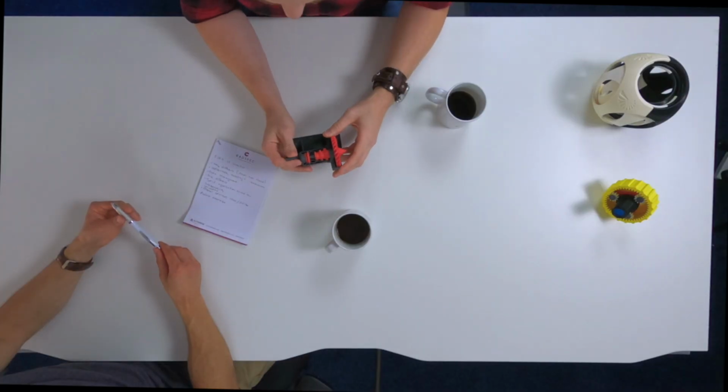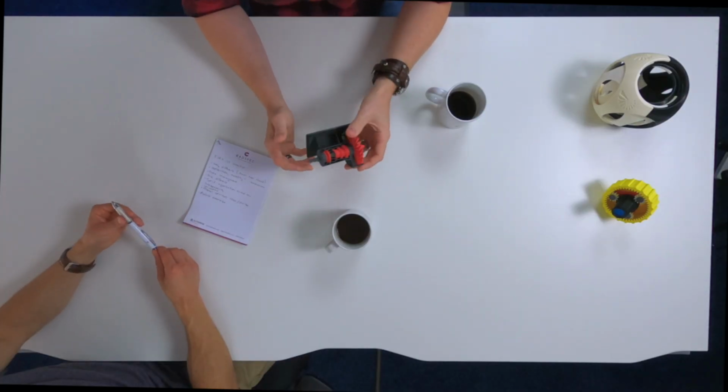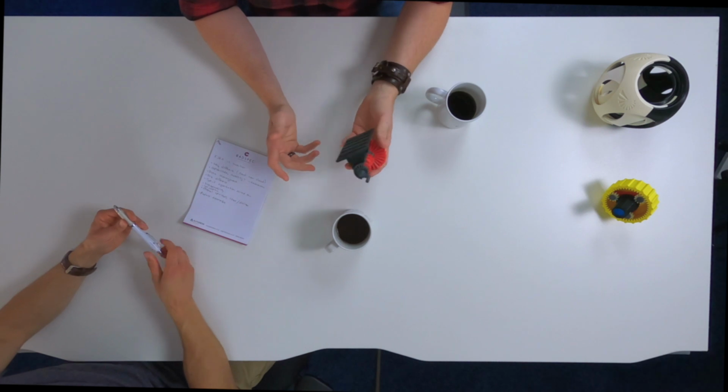And even in Inventor, there's another example we've got here, if you're looking at things like tolerance analysis. Inventor has very strong tolerance analysis tools available in it. Similar stack-up, haven't you? Yes, where you can actually have a look at what the tolerance stack-up is and how individual tolerances affect my cost as well as the overall tolerance of the whole assembly.